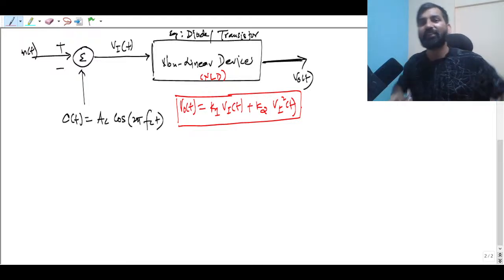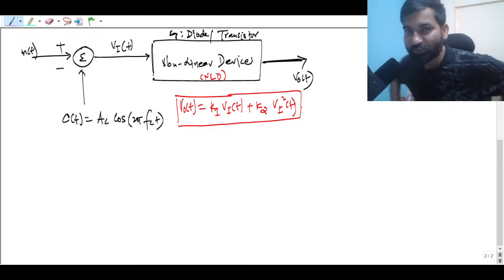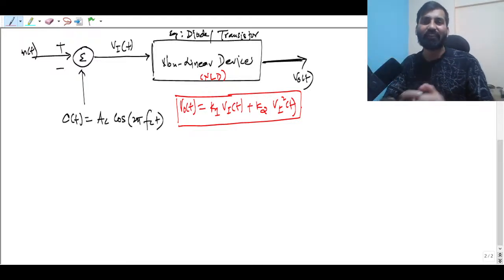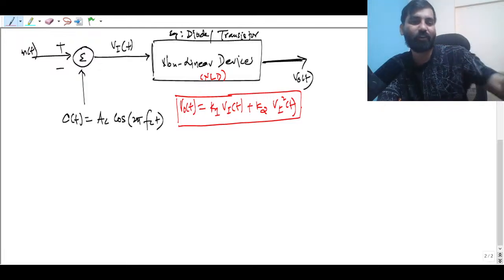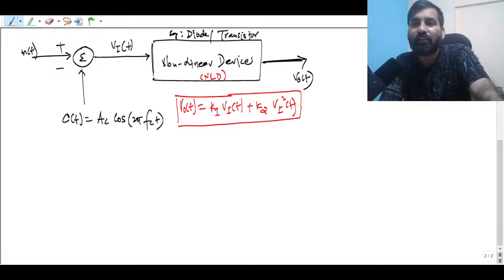The reason is, if you are modulating your signal, your signal is going to get translated to high frequency. That is the advantage, because the dimension of the antenna will be very small. You will be able to physically realize the antenna height, and there are many other reasons.